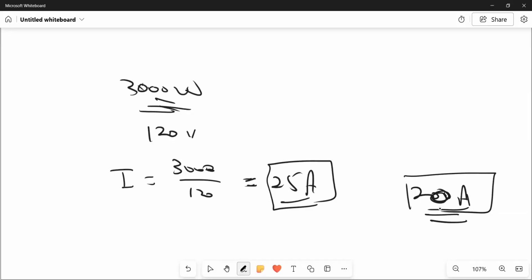At other times, if you have a bigger breaker, maybe a 30 ampere breaker, guess what? It's going to allow the current to pass, but your switch can't take that. Remember, the switch is wires connected in there, and that current might very well burn the switch. The switches are very inferior. So lots of people have this trouble because this current is too large.